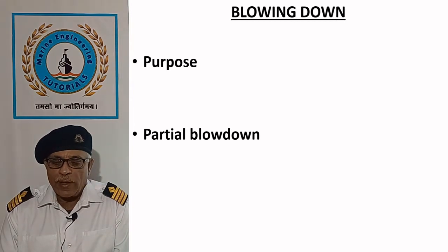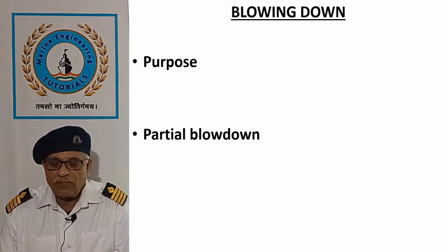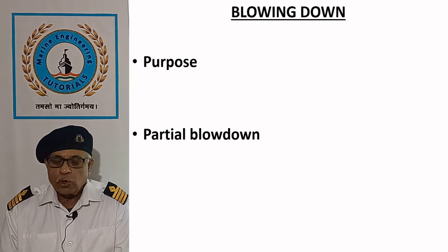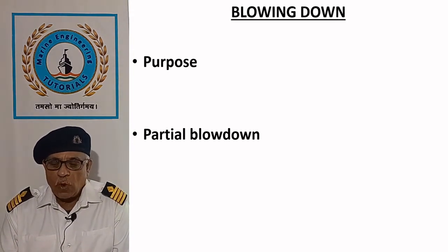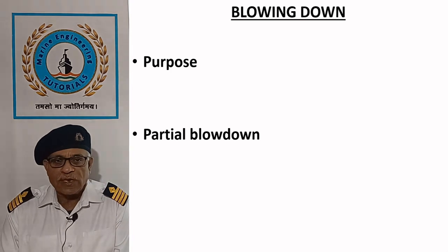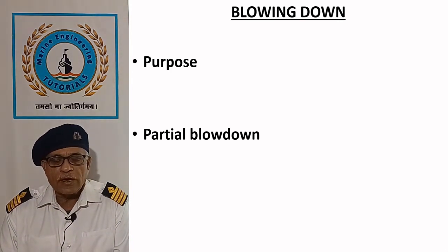Partial blowdown should be carried out frequently, that is every day for water tube boilers, for a short period of time by quickly opening the valve, thereby creating turbulence at the bottom of the water drum or header in order to remove the precipitates. It also reduces the concentration of dissolved salts in boiler water, including the concentration of treatment chemicals such as alkalinity, phosphates, hydrazine, etc.